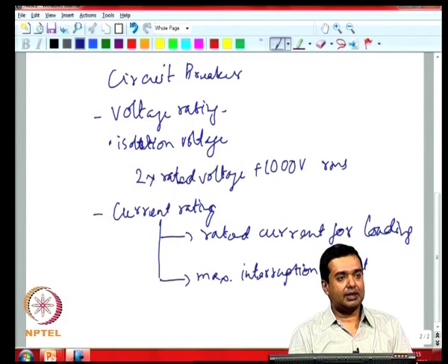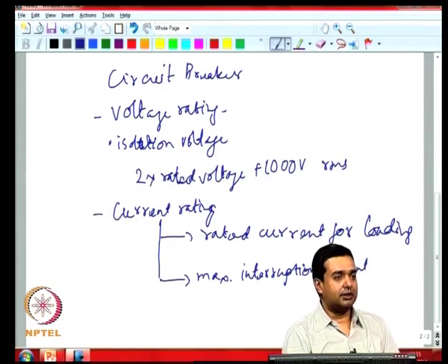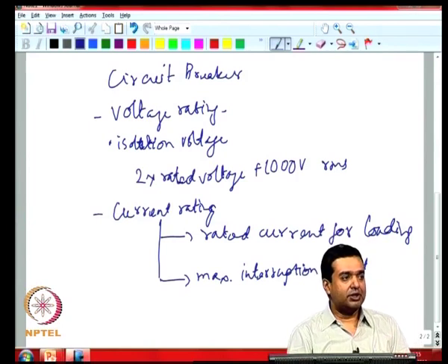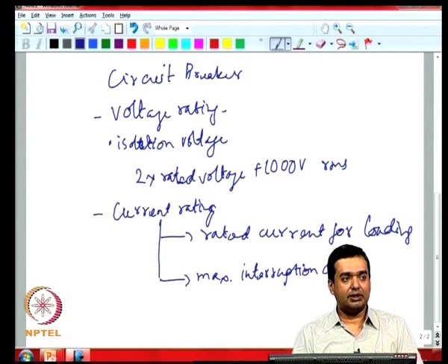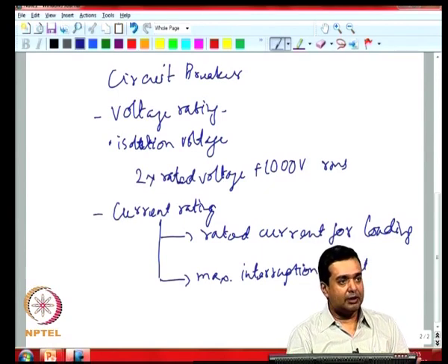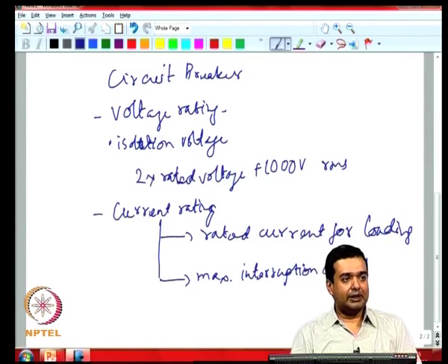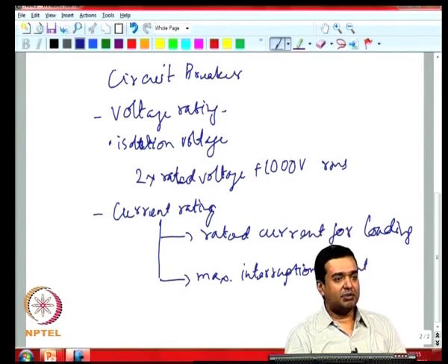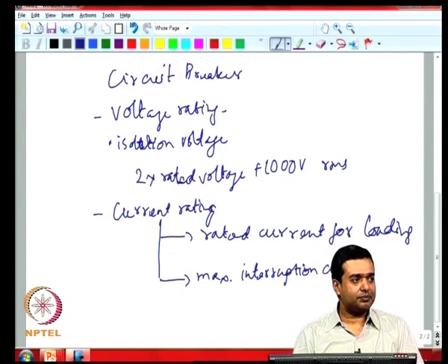If you are looking at just an isolation switch, you are looking at the ability to maintain isolation voltage. You are not even looking at the ability to interrupt load current. So, depending on the type of switch that is being used, you would have different levels of complexity. Because the circuit breaker is intended for applications that handle much higher fault conditions, your circuit breaker would be more expensive than just a contactor.